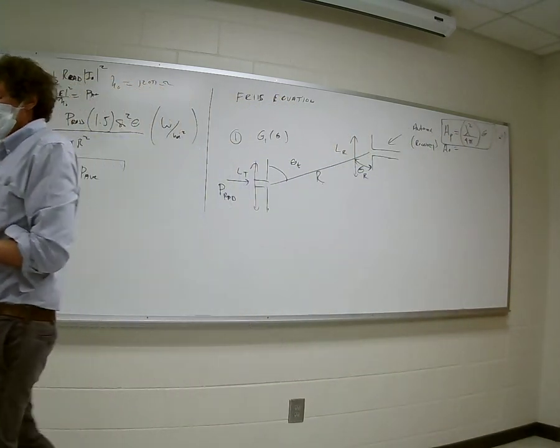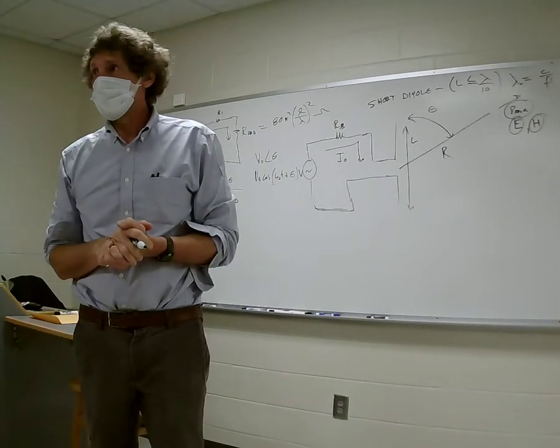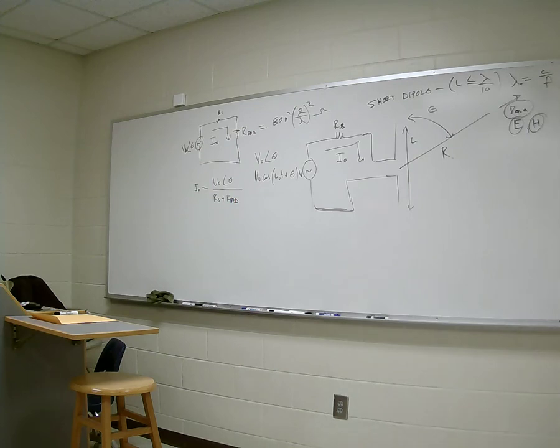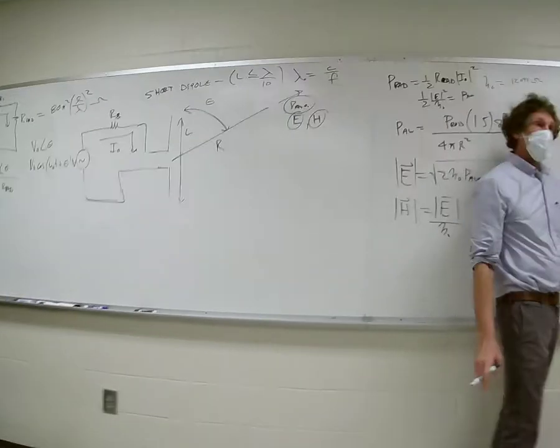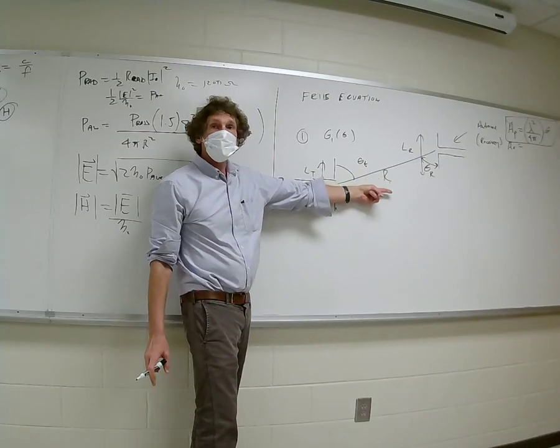So the gain of the antenna is proportional to the aperture, but you notice the size is dependent on lambda squared. You got that? Now, if we assume for a second both of these are short dipoles, I want you to just follow this. Remember, the gain of a short dipole is 3/2, or 1.5, and that angle is 90 degrees, isn't it, class?